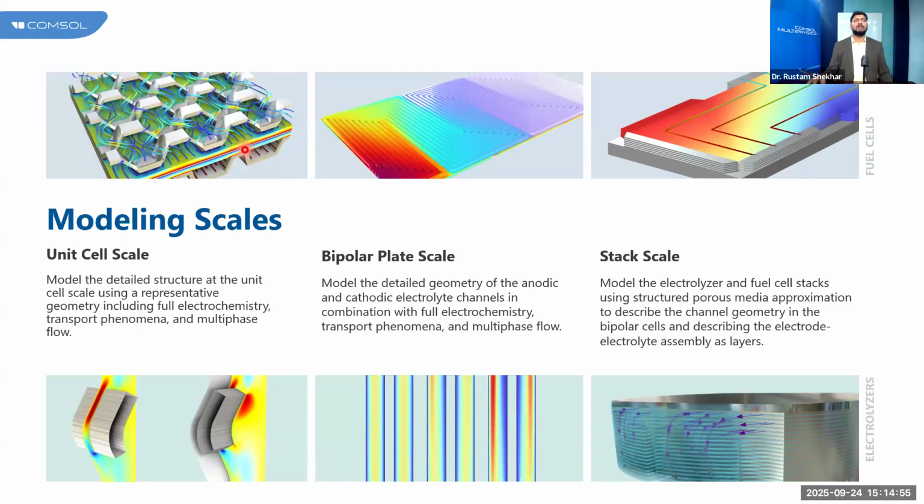So basically, there are three layers which are doing all this magic, where fuel is coming into the channels, going to the electrode. At the electrode, it is reacting, giving electrons in case of fuel cells based on the anode or cathode, and then the unreacted fuel is passing through. So that way, the entire magic happens at these three functional layers.